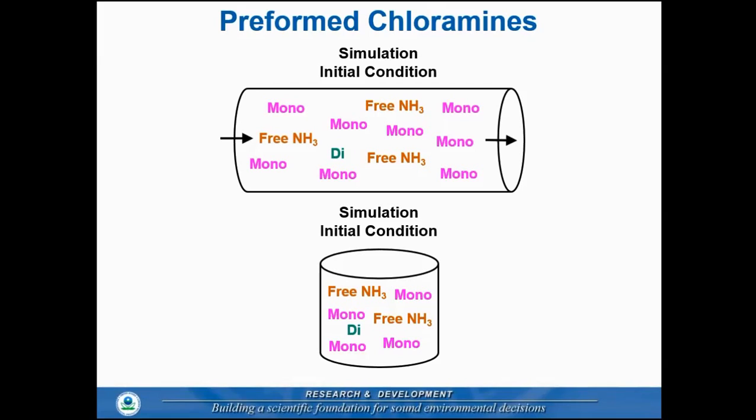So what this is going to be, it's going to be akin to taking, say, a sample of water leaving a chloramine treatment plant and just holding it and then looking at how long the chloramines stick around with time. Or you could take a sample out in the distribution system and do the same thing. But any case where you have preformed chloramines, essentially no free chlorine initially.